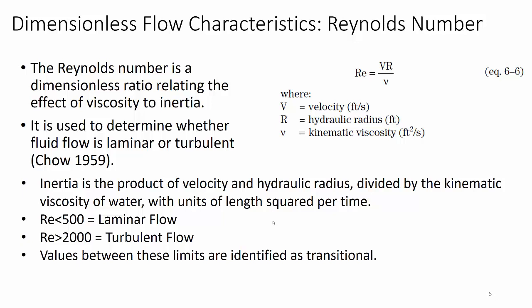Laminar flow, of course, is flat flow over a surface. Think about slow flow over a sheet of glass at a slight angle. That's laminar flow. It means layer flow, like laminar clouds. Turbulent flow happens when the Reynolds number gets high, when velocity gets high, and then with the relative kinematic viscosity of water, then turbulent flow occurs, and you start getting, just like with gas and with clouds, mixture and non-linear flow as it hits surfaces, especially the bed surface and rocks and other things. And that actually decreases the velocity.